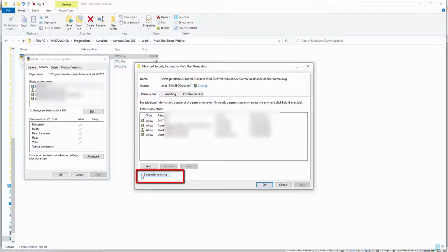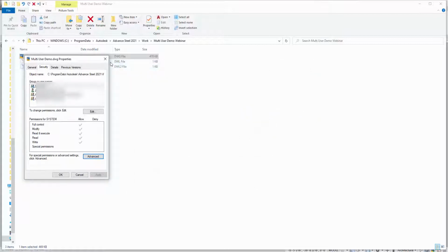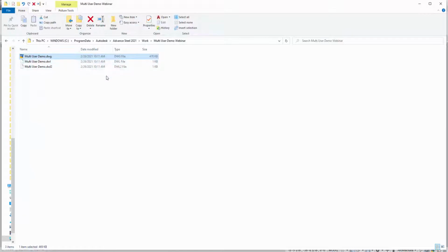Once that's done, we will now explore the multi-user panel, create a user one and save it to the correct location where we will connect it to the network model, make modifications using the checkout by selection complete for the columns and checkout partial for the beams on the mezzanine level.